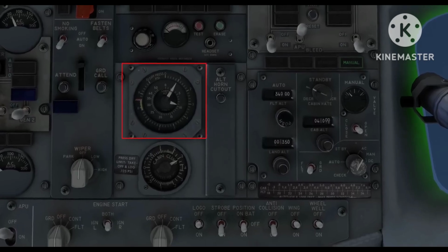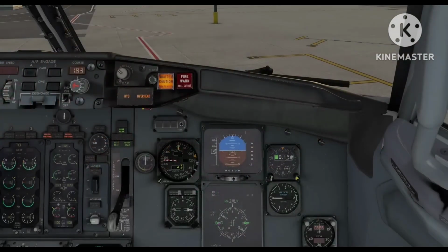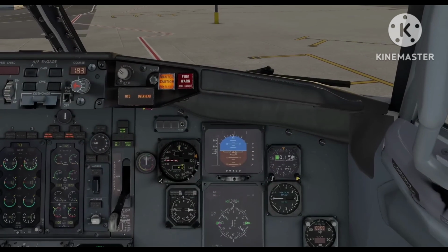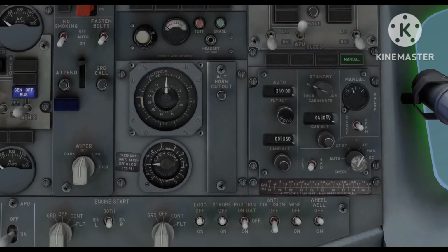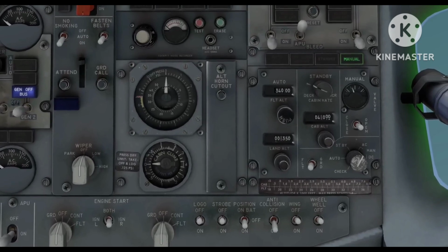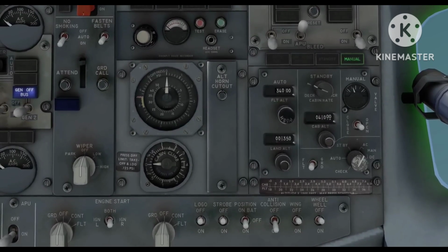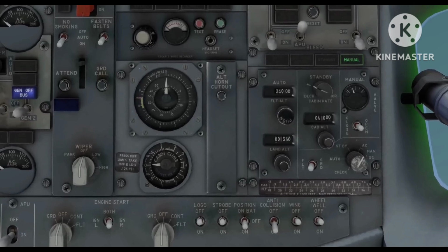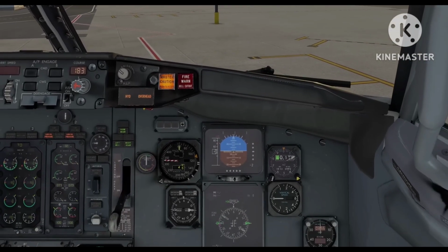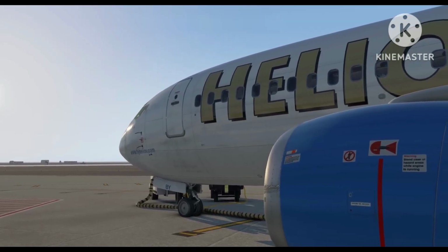In an aircraft, maintaining proper cabin pressure is crucial for the safety and comfort of passengers and crew. As a plane climbs to higher altitudes, the outside air pressure drops significantly, making it difficult to breathe without supplemental oxygen. To counteract this, the aircraft's pressurization system adjusts the cabin pressure to levels similar to those at ground level, where breathing is easier. The pressurization mode selector switch is essential in managing this process.